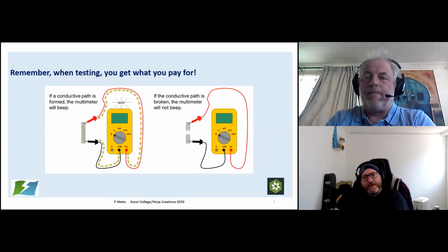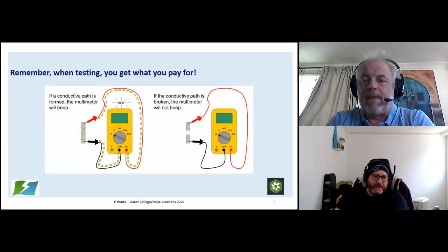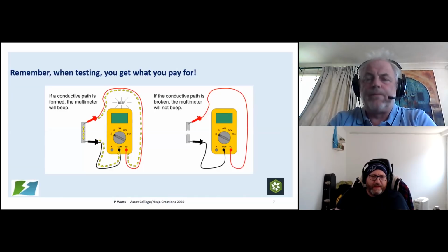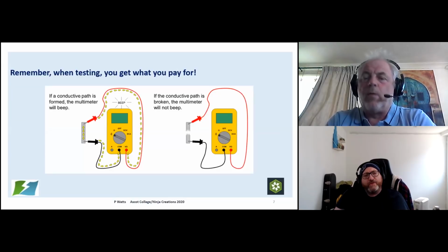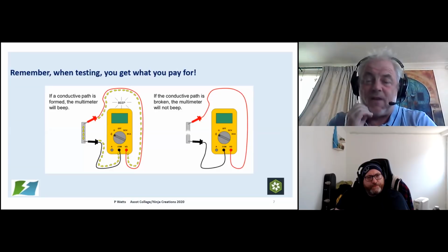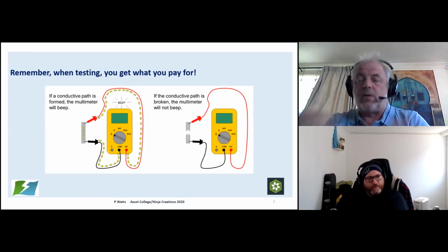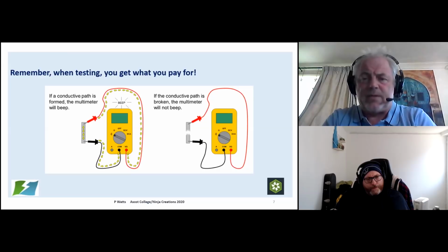Dave's just mentioned the K squared S squared, the I squared t, for thermal withstand. That's just how you verify the final thermal withstand. We'll probably add that to the live testing one. Well, that will be in the live testing. I think we'll see as we run through this. We wouldn't have had time to look at live testing, not to give it proper due care anyway.